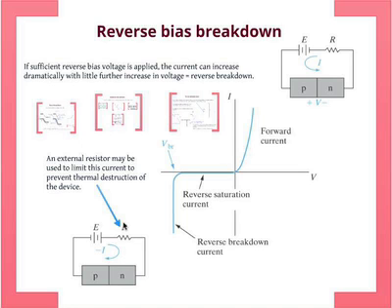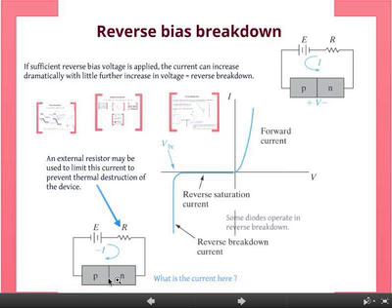Right? When you apply an external resistor, then that will have a voltage drop, which will determine how much current will flow through it, basically. And since it's in series with the junction, that determines the whole current in the circuit. Okay, so make sure you keep that picture in mind, because when we go into the physics, these things will become abstract, but keep that big picture of this simple circuit in mind.